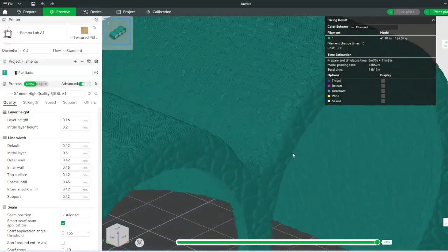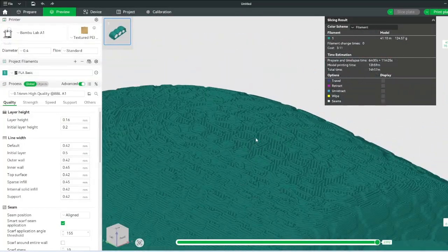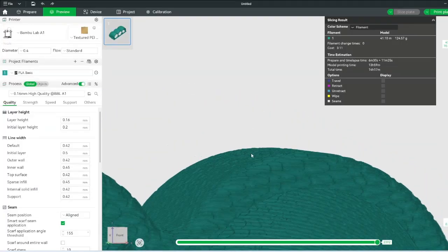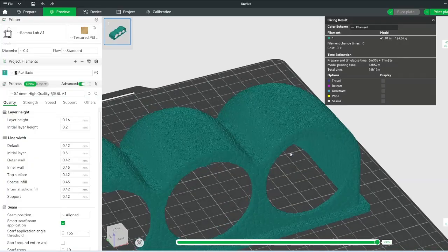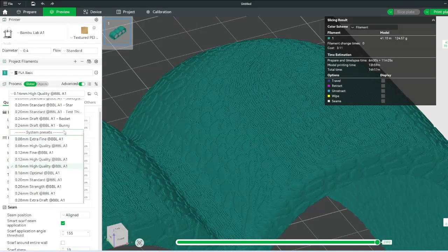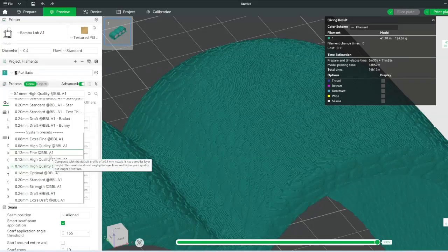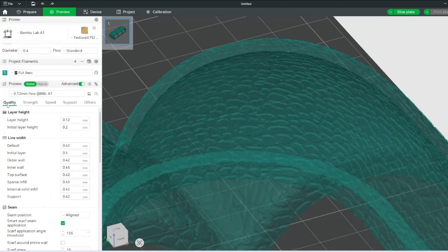But yeah, a consideration as well is to consider the print orientation. You can see on top, the texture doesn't get printed as well in this particular part because we have this kind of horizontal overhang. And it's just the unfortunate truth of it: if you really want this high detail, you have to print in high detail. Sometimes there's just no way around that. So going to 0.1 even would probably be the way to go here.